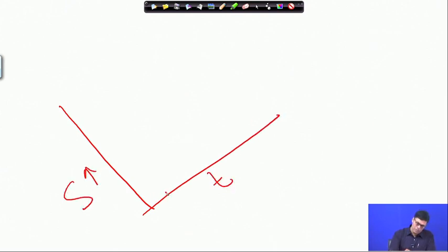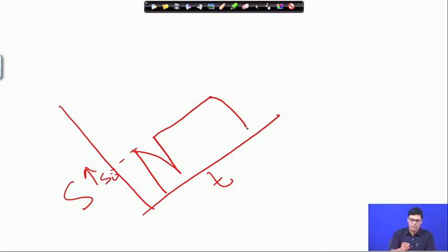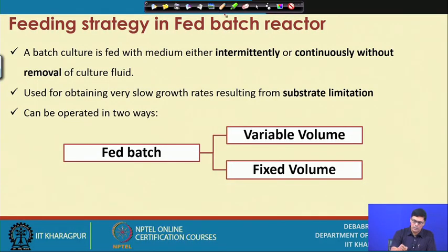So, what we can do is first start with the volume and let the reaction take place. Then we start feeding, the substrate decreases, and then again we feed until we come here, this is the S0 value. Then we continuously feed in a manner so that this value remains S0, and finally when we reach the final volume, the substrate concentration decreases to this. So, these different types of feeding strategy we can use in the case of an immobilization system.